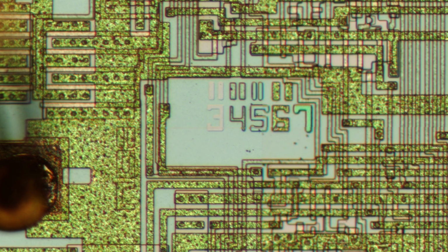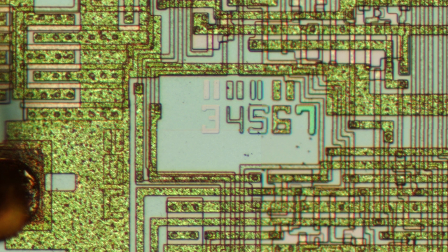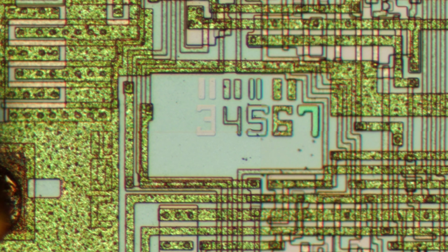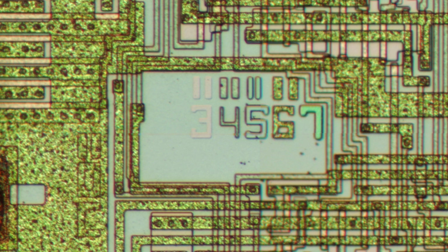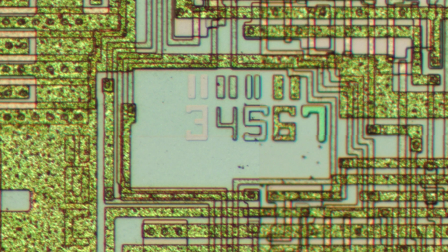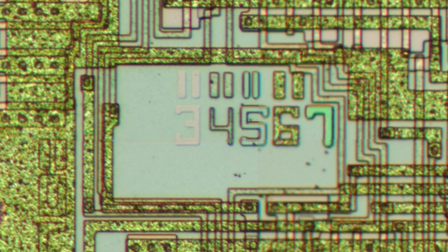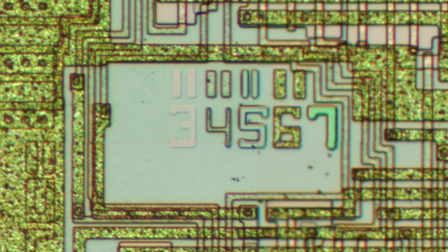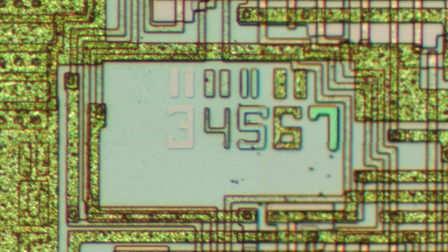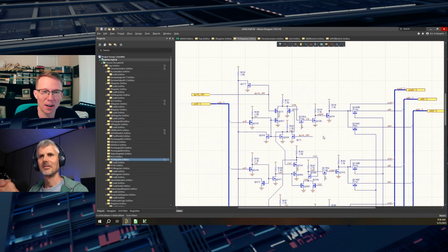And one thing I really liked about that was it was like 7, 6, 5, 4, and then you can't read the other numbers because they're invisible, because they're like diffusion or doping or whatever. Yeah, they're the ion implantation layers. Yeah. So layer 1 is the first diffusion, which, of course, you can use to build your transistors and all of that. And then the next 2 layers are the ion implantation. And that's what you can't see because you've got your ion implanter and it's literally an electron rifle or an ion rifle. And it's just firing ions into your substrate at a predetermined depth. And so you're not going to see anything from the outside.